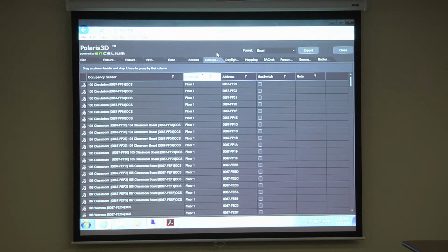No, you can daisy chain, because the last device is one device plugged in and the other end is open. But that's what I'm saying. Okay, I'm on channel 3, but I'm all the way down at the end of the building. Instead of running out of the port of the ECU on channel 4 clear across the building, you're saying I can tap off 3 to get a 4? Yeah, same channel. You can just tap off and catch the other devices in that vicinity, even though it's already on channel 3.